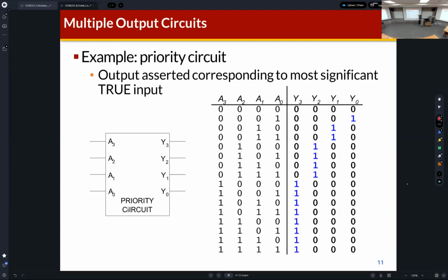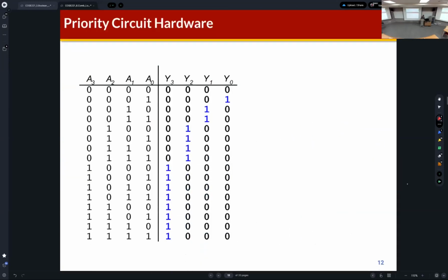There are 4 inputs here, and to make the Boolean equation for Y3, we need to focus on the result of Y3 from these 4 inputs. Then we can apply the SOP form or POS form to write the Boolean equation. As we learned, we can apply the SOP or POS form.